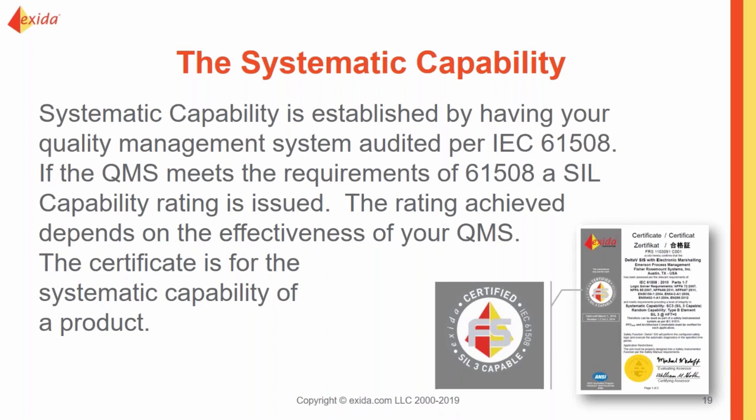Well, this is saying that whatever this device is, whether it's a logic solver, a sensor, a valve, anything you can think of, this can go into up to a SIL 3 CIF. It is a limiting factor.